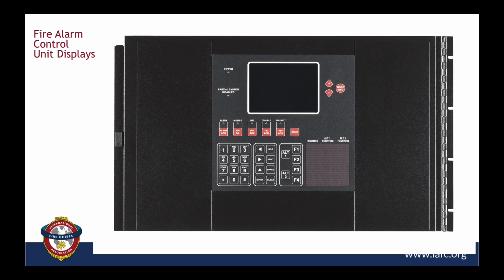These are actually programmable function keys that are there for the ability to allow maintenance, or even during a fire inspection, you can push F1, for example, and you can turn off all the fans and disable the fans in the building. F2 could be unlock all the locked doors in a building. Things that are controlled by event functions when the panel is going into alarm. These buttons can be used to program and simulate certain conditions accordingly.